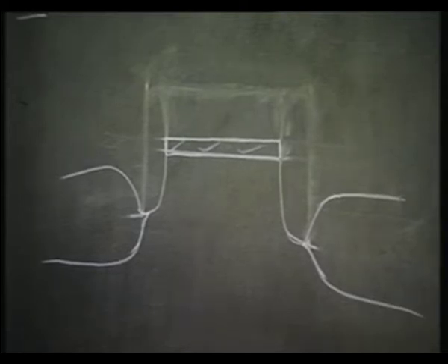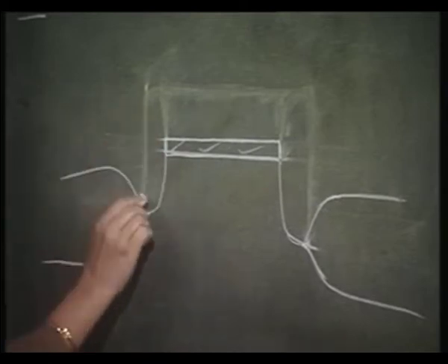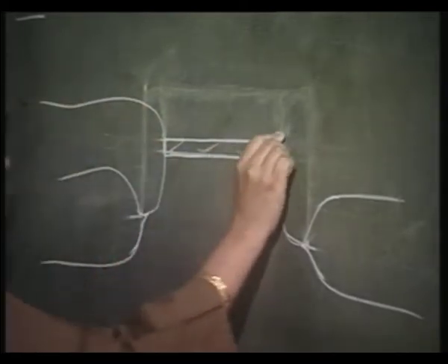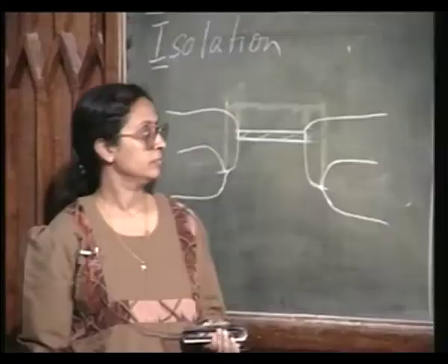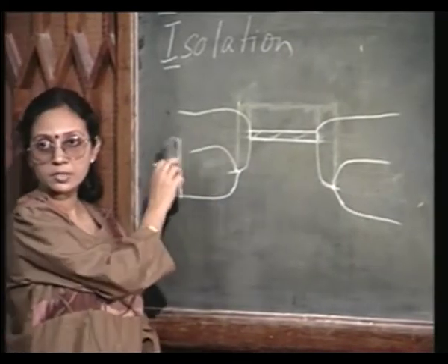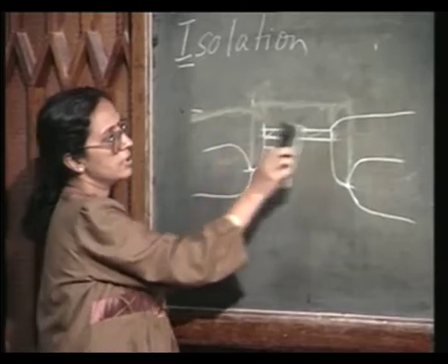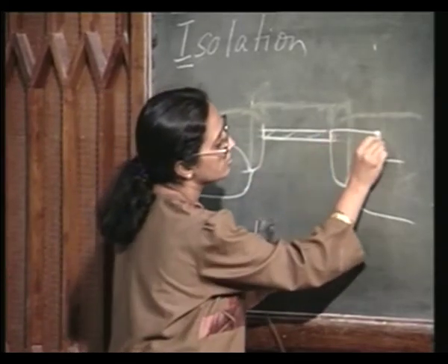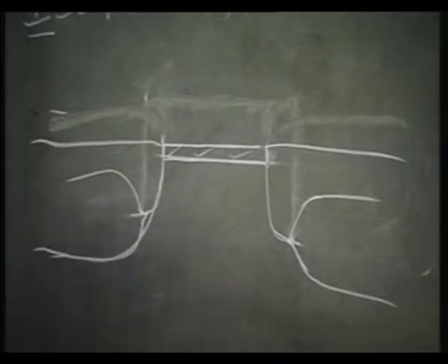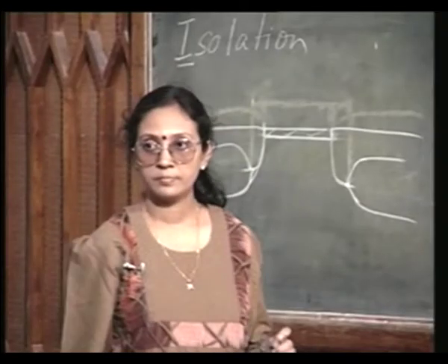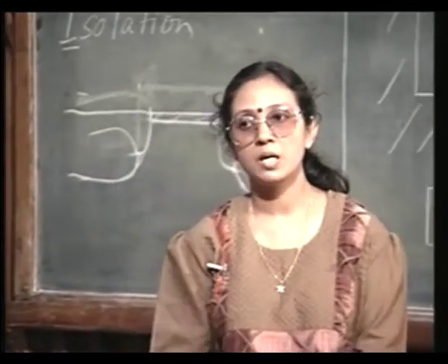Okay. Now, you do another CVD deposition of silicon dioxide so that these regions are all filled up. And then you can planarize, you can just partially etch the silicon dioxide layer so that nothing has penetrated in the channel region. So, this is the side wall masked isolation.